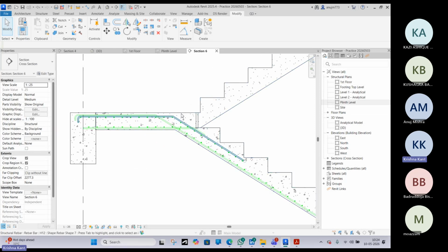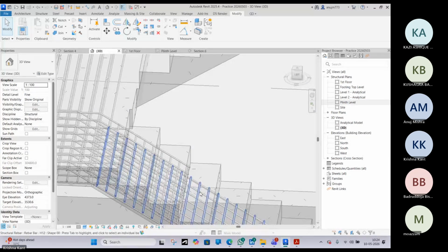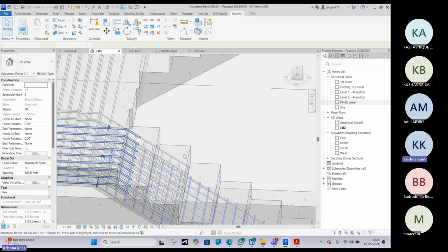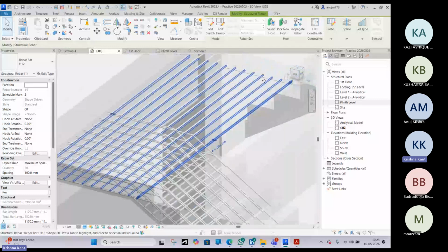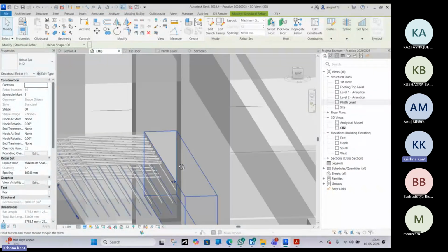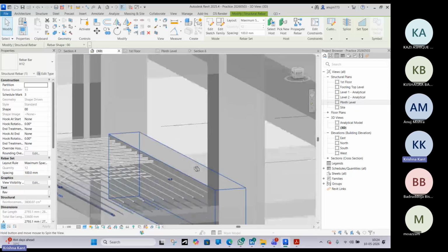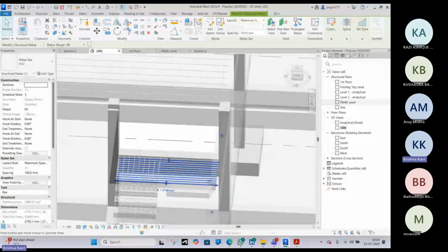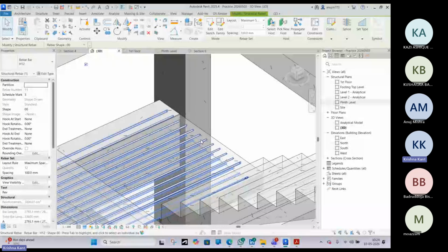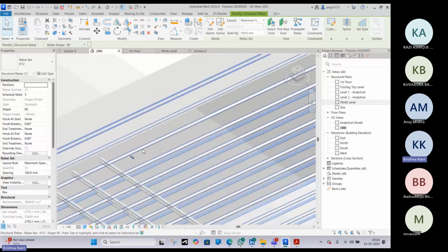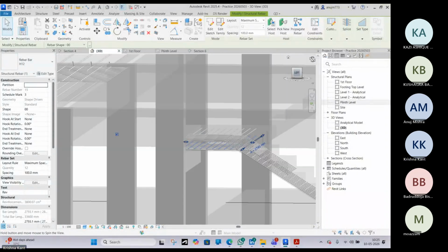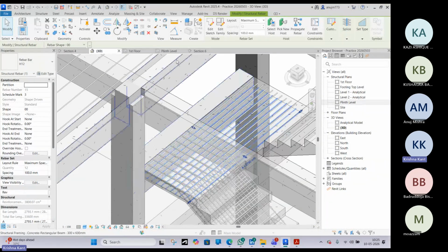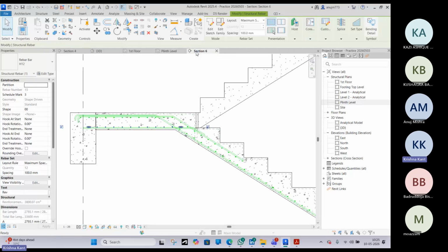Understood? Now, one thing you can notice, this rebar is up to here, and automatically when we have provided these rebars, it's extended till this end, right? That is good only because we have to provide these rebars in this region of the slab. Okay, that will not be separate. This is like in one go only we have to provide. Okay, but we have to use this rebar.